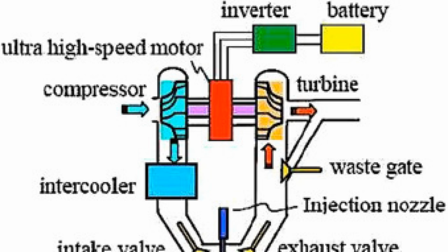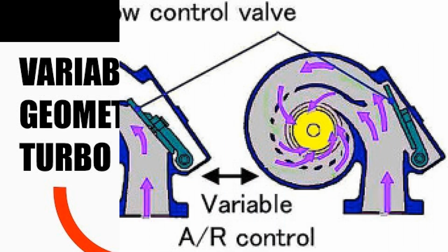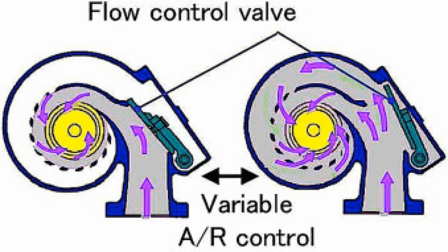The design of a fixed geometry turbine is always a compromise between speed to efficiency zone, boost rate and peak power limit. These parameters are influenced by the diameter of the gas flow channels, the ratio of inducer to exducer area, radius of housings, wastegate valve design, and blow-off. But because the turbine characteristics are laid down at the design stage, its working area is rather narrow.